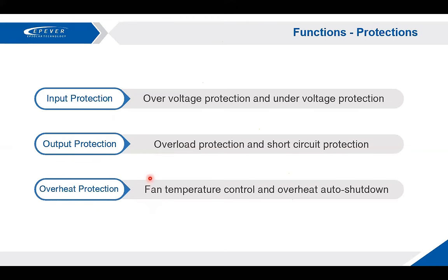And there are some LED indicators that reflect the status of the inverter, and a buzzer will start buzzing in some conditions such as input under voltage, as I mentioned, input over voltage, over temperature, or load short circuit, overload, output voltage abnormalities. And there is a complete list of these kinds of faults in the manual, and you can have a look at them. An important note is not to reverse the polarity of this device on the input side. So this device is not protected against battery reverse polarity. Otherwise, it will blow the fuses. So the installers have to be careful about it.